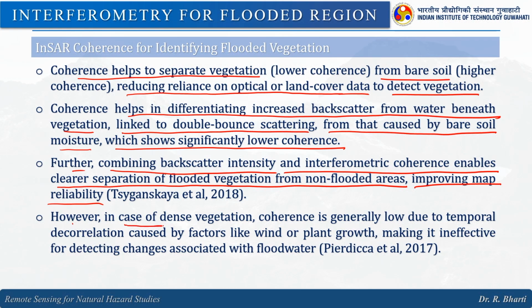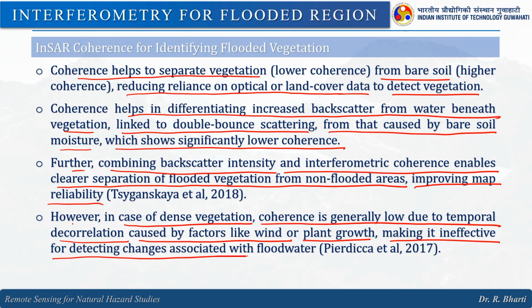However, in case of dense vegetation, coherence is generally low due to temporal decorrelation caused by factors like wind or plant growth, making it ineffective for detecting changes associated with flood water. So, when we use InSAR, we have to be very careful about why this coherence image is coming, why these values are coming. We need to understand and answer that.